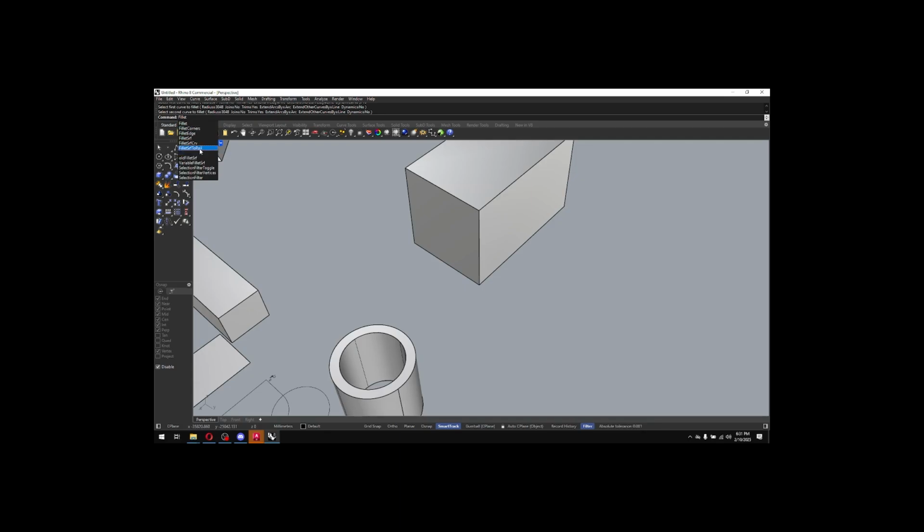What is this one? Fillet surface corner. I'm not even sure what that one is. The one you probably want to pick first is going to be fillet edge. I think that's the one you typically think of when you're making an edge like that on a surface. So just like we did before, let's make our radius 10 feet.